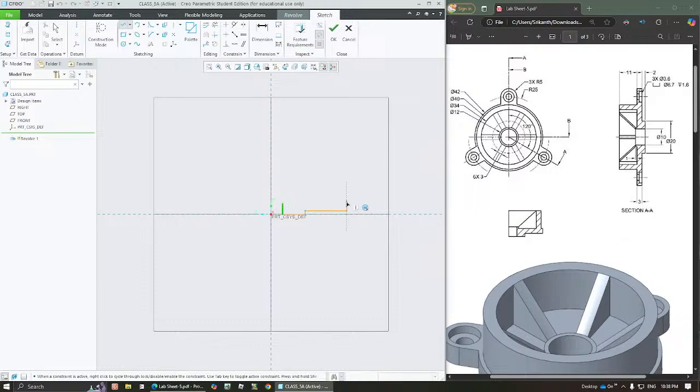Once again right click 2 times, and then a little inside and go up, and a little left, right click 2 times. We don't want any equal constraints to be applied, whereas here we definitely need an equal to constraint because we have to come back to this. Right click 2 times, up, and a little left. So come out of this.